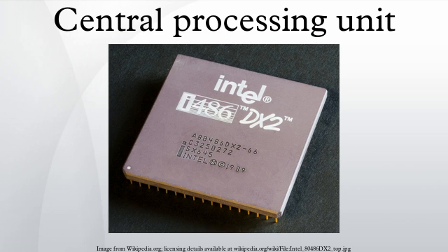Design and implementation. The basic concept of a CPU is as follows. Hardwired into a CPU's design is a list of basic operations it can perform, called an instruction set. Such operations may include adding or subtracting two numbers, comparing numbers, or jumping to a different part of a program. Each of these basic operations is represented by a particular sequence of bits. This sequence is called the opcode for that particular operation. Sending a particular opcode to a CPU will cause it to perform the operation represented by that opcode.